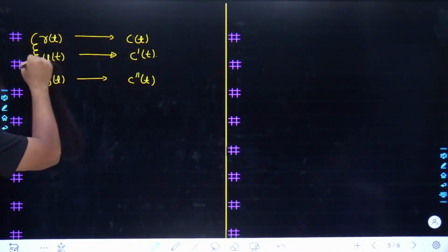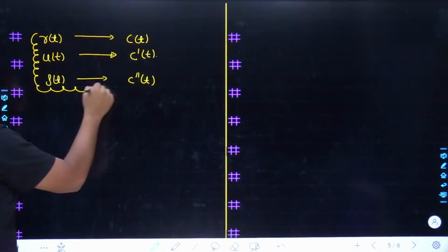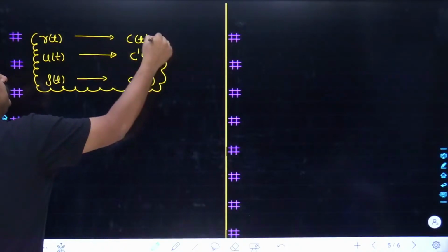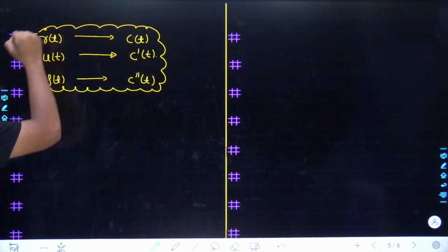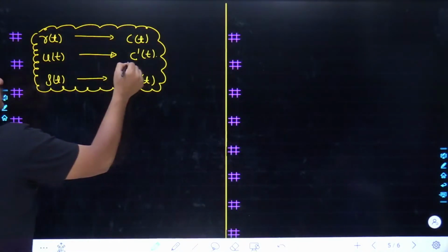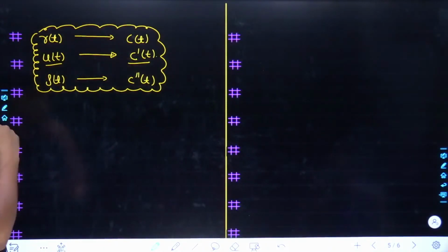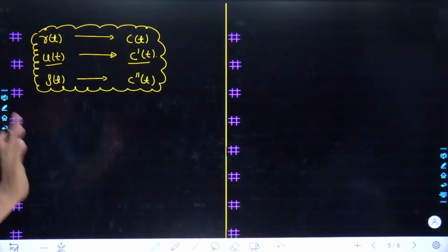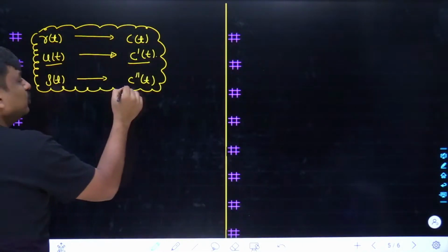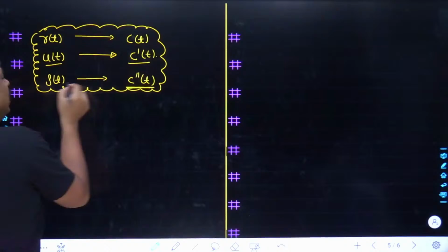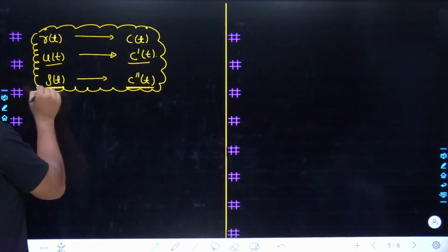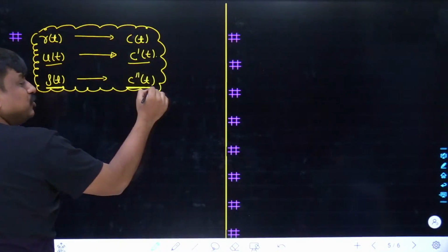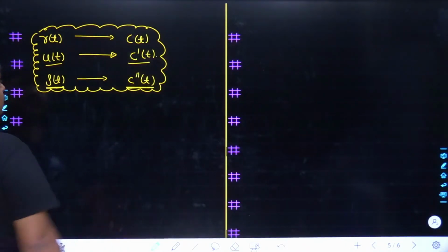This sort of problem, based on this concept, many times keeps coming. In this problem, what have they given? They have given the output when the input fixed to the system was u(t), and they are asking what would be the transfer function. How did I calculate this? Obviously, once we know this c double dash t, or I can say once we know the output corresponding to the input as the unit impulse, I will take its Laplace, I will get its transfer function.